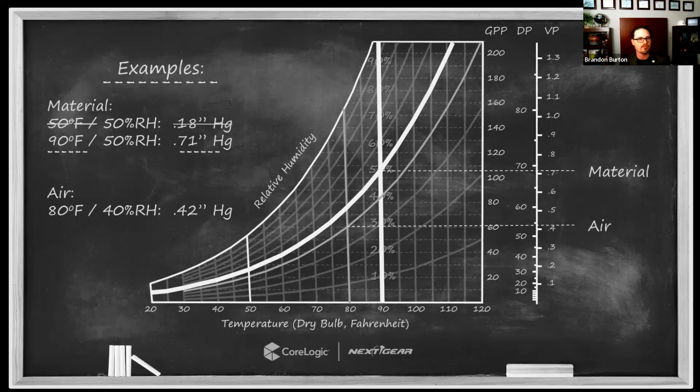So what would normally happen at that point is you'd make an adjustment to make the material warmer, whether it's raising the air temperature in the building, maybe it's a subfloor and there's a crawl space underneath. So you raise the temperature of air in the crawl space, that makes the subfloor warmer. Or maybe it's a wall cavity and you move to using an injection system to inject some warm air into the wall cavity, right? You make those adjustments and then you remeasure. And maybe it's just a laser thermometer that you're remeasuring with to get a quick, immediate temperature, and just shoot a temperature and say, okay, now the wall's at 90. So now you go back to the chart and you ask, is 90 enough?